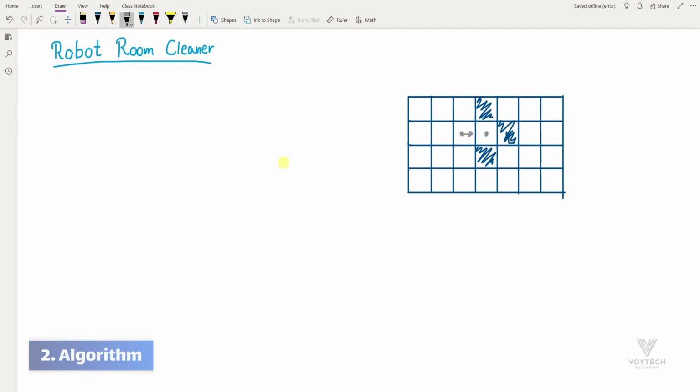And constrained programming means that we mark visited cells as obstacles, or better to say virtual obstacles. So if our robot was there before, when our robot moves to the next cell, which is here, it should see this cell also as an obstacle.